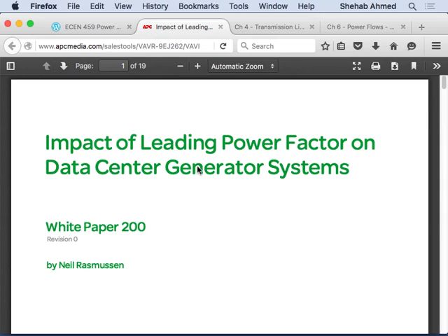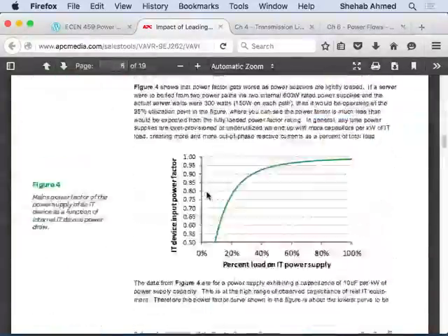Typically, all loads are lagging power factor, but a data center is computers. It's all electronics. Power electronics people know that everything likes to be at unity power factor. So fine, we can make everything unity power factor by power electronics. But in doing that, we have to use these power converters that have input capacitors everywhere. So what if I decrease the load on the UPS, or I turn off everything that I have? I still have the input capacitors in the system.